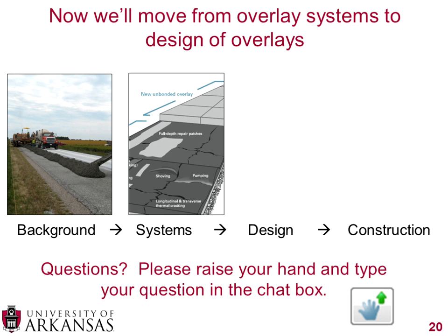Now, in theory, you are able to do some relatively minor repairs to get rid of the worst of the rutting or the cracking. But in theory, if you have a structurally sound layer, you should be able to place a bonded concrete overlay over that. It will bond together, and then you'll get the benefit of having that thicker pavement structure, and that will allow you to have a higher load carrying capacity.